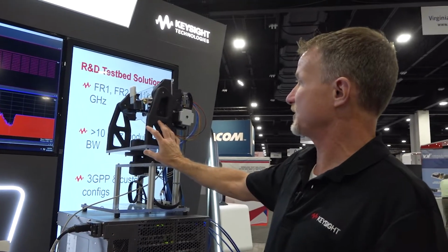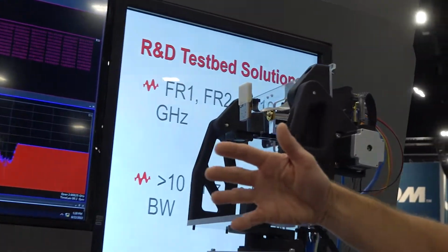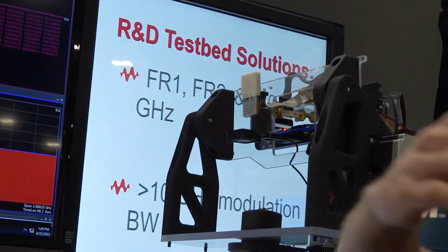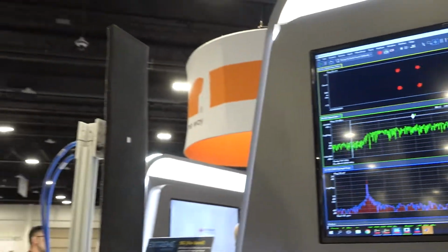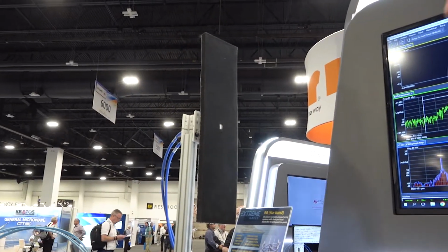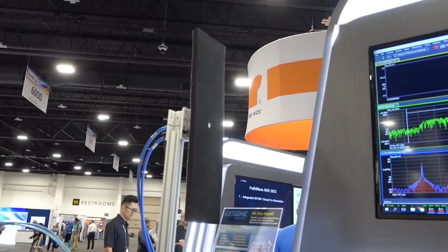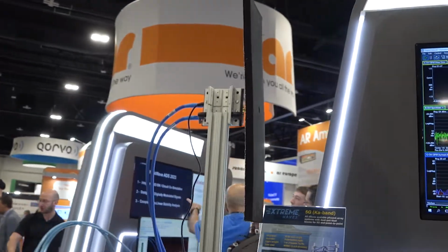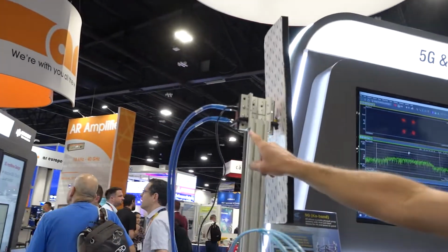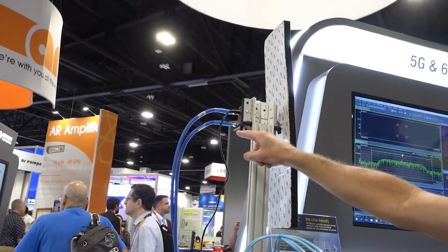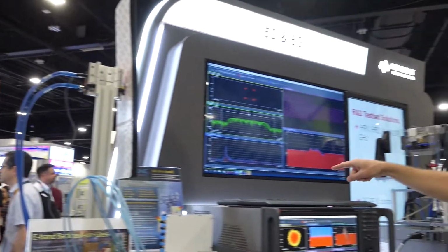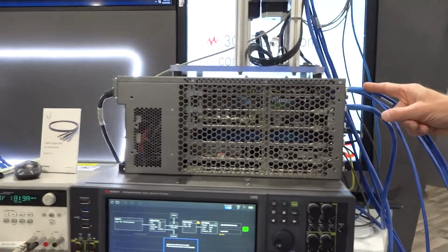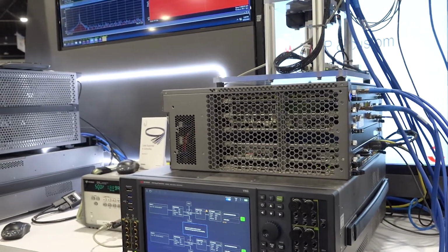You'll notice that the antenna positioner is rotating periodically. When the antenna positioner moves, we're electrically steering the beam back towards our probe antenna, which you can see over there. We have some absorber material to cut down on the reflections, but it's captured to the horn antenna. Just behind that absorber is a VDI down converter. Also at D-band, we take the output from the down converter at about 15 gigahertz. We run that back along the table, back into the digitizer, where we capture those signals and then feed them to the VSA software for demodulation.